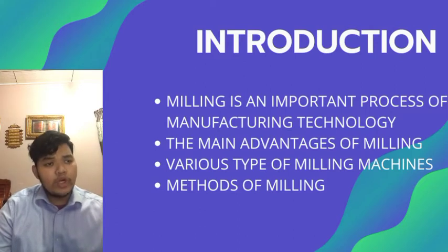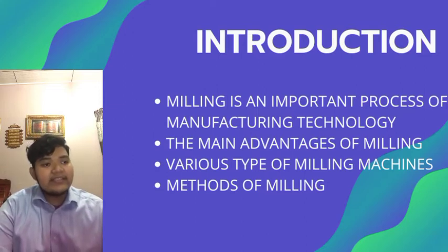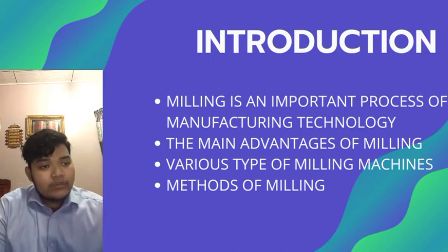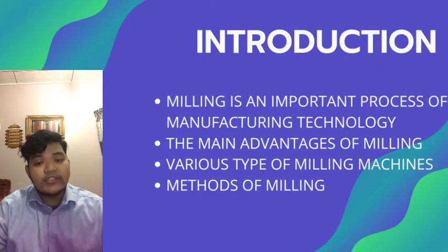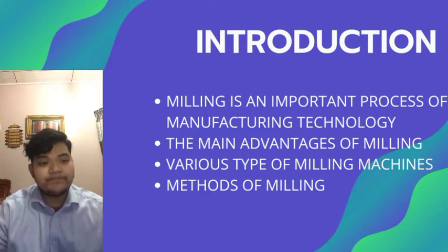The next one is copy milling. This technique is used where a design or cut is difficult to make by itself. Hence, it is first made in the form of a master template, which is then used to guide the tool path. Basically, the template acts as an original form from which the other parts are copied, just like you would photocopy a document from an original paper in the Xerox machine.